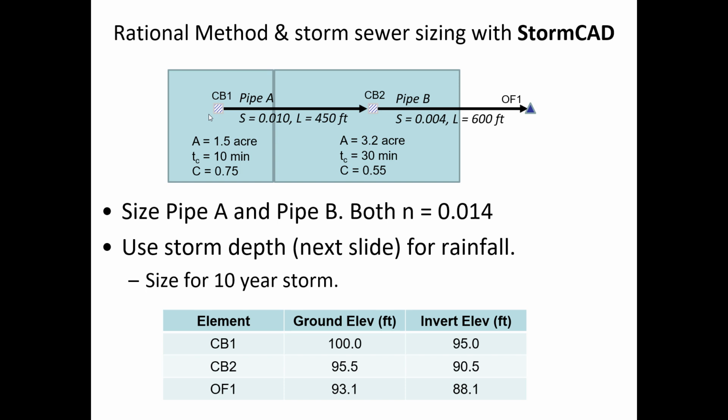In reality, if a grate is along a road, and let's say that the street is on a slope, the water may flow over the grate and only a fraction of it would go down through the grate and into the vault, and some of it would continue onward. So inlets aren't always 100% efficient at intercepting the flow, but we're going to set it up so that they are 100% efficient.